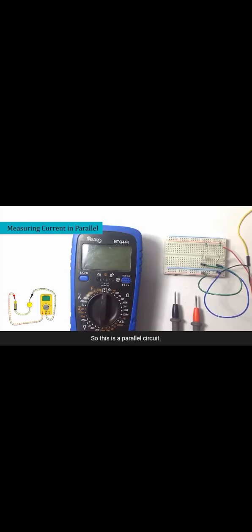So this is a parallel circuit. Now let's check current across the parallel circuit. As we know, the current divides in parallel circuit. So let's check. We'll take the two probes of the multimeter and shift the knob to the current part.